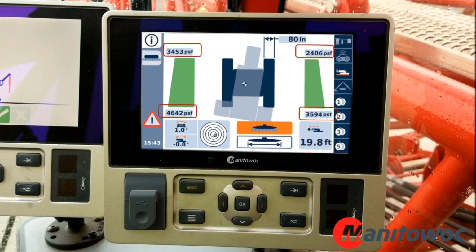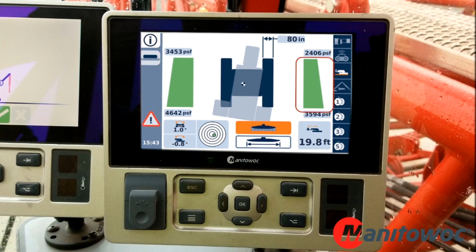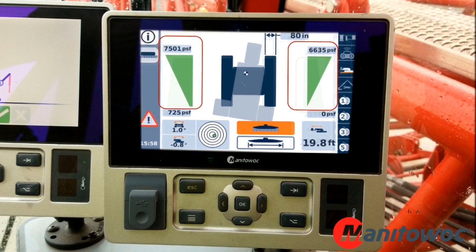Ground bearing pressure is shown by these four positions. These trapezoids represent the distribution of ground bearing pressure from one end of the crawler to the other. The size of the trapezoid at each corner is drawn as a proportion of the maximum corner ground bearing pressure.